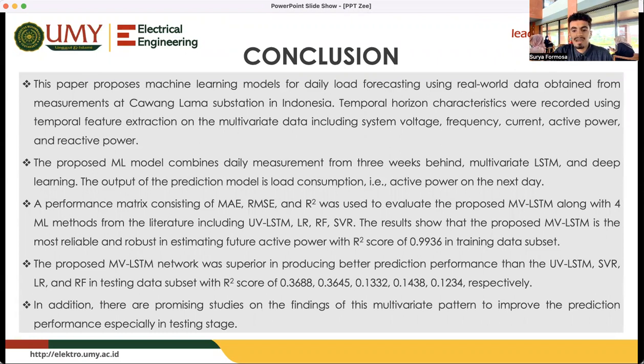Temporal horizon characteristics were recorded using temporal feature extraction on the multivariate data, including system voltage, frequency, current, active power, and reactive power. The proposed ML model combines daily measurements from 3 weeks behind, multivariate LSTM, and deep learning. The output of the prediction model is load consumption, active power the next day.